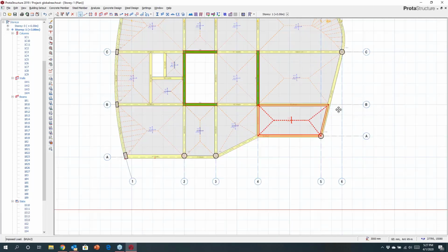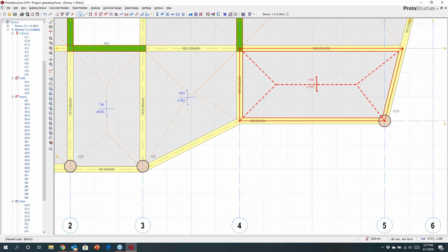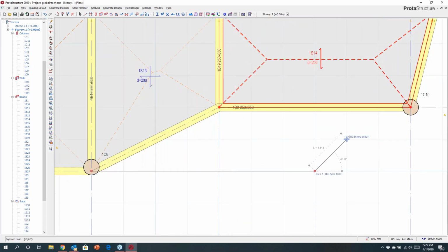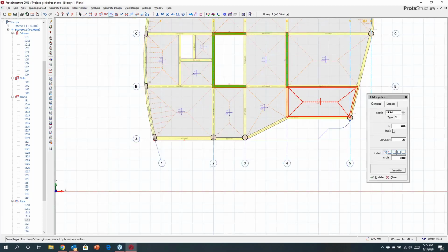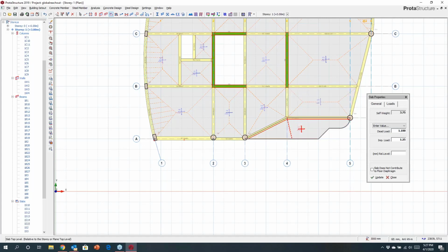Now, if I've got unusual geometry, we can also make use of what we call sketch lines. You can use these to help you sketch out a profile. So if I had maybe the side of the building, I've got a funny slab, and I can use sketch lines just to help me sketch this profile, and then we can use this to help define that element. So I might want to put in an edge slab there. We can key in the thickness of this. Maybe I want to drop it, maybe 100. And then I can use that boundary just to help me create that slab.